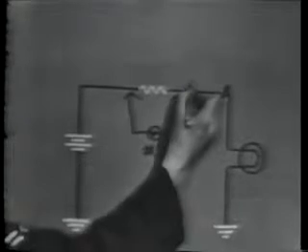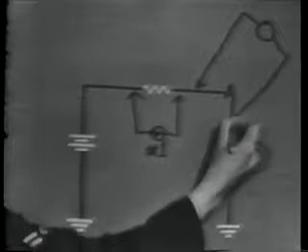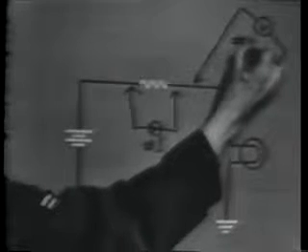What about the voltage across point A, the open in this circuit? You can see by connecting the voltmeter across this point, it will complete the circuit, which will allow a small current to flow. The resistance of the voltmeter is much greater than that of any other component in the circuit. So, in effect, it will read all of the applied voltage.